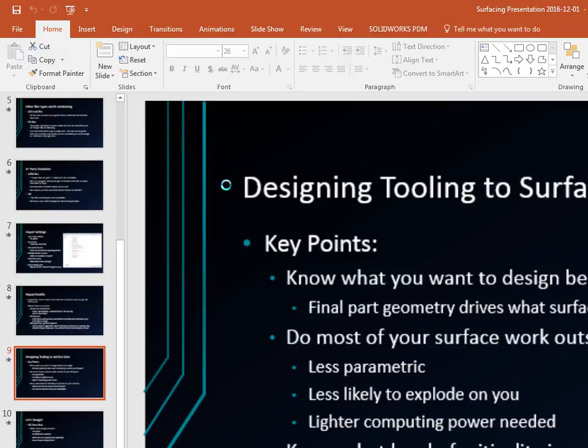So here, if I want to make a fillet that's bigger than 0.263, say 0.3, it may or may not solve. It's not going to solve, because you can see it's got some junk going on there. Even though I'm getting a preview, I doubt that's going to solve.